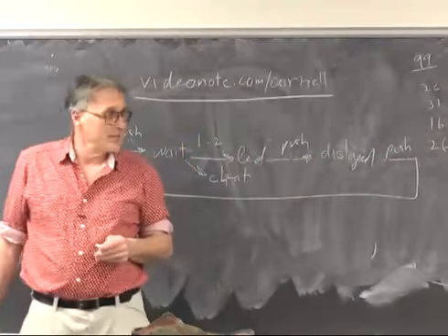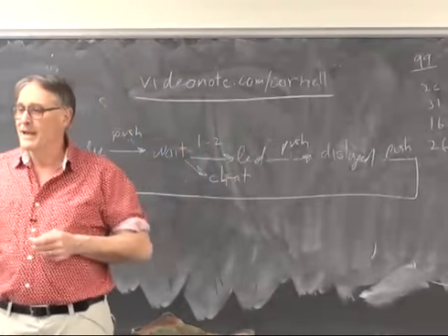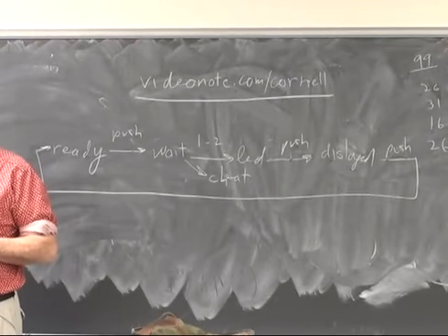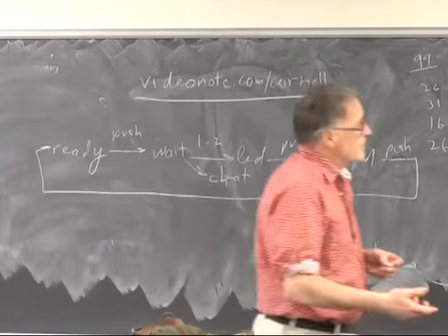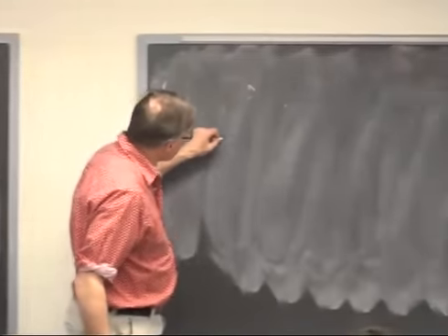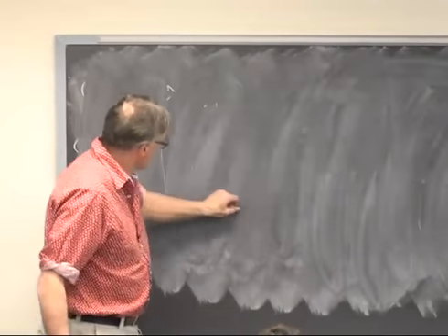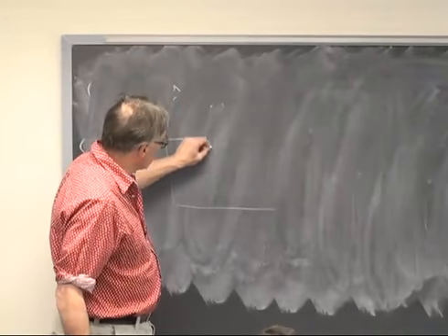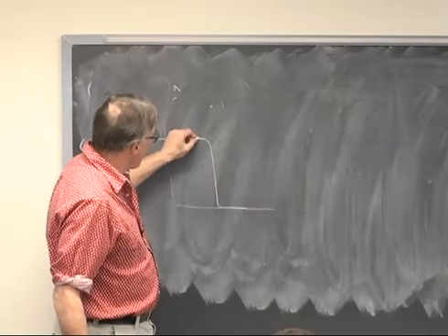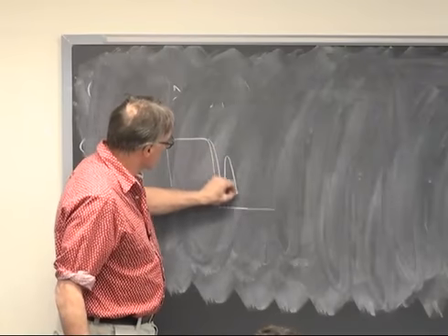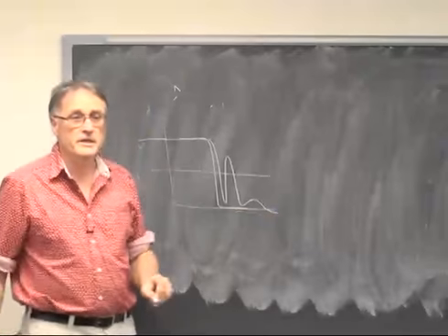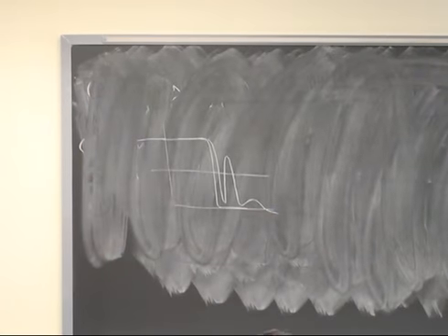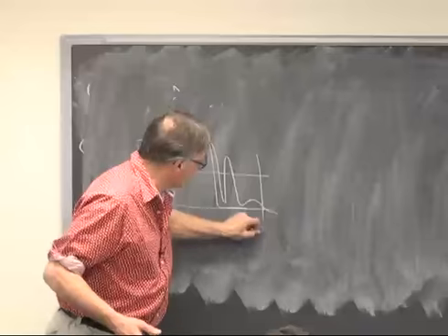Now, the thing which makes this interesting is that mechanical buttons all bounce. They're spring mass systems. They oscillate. So when you push a button, you think the voltage should do this, but in fact, it does this. And it can pass the CMOS transition voltage n times in about 15 to 30 milliseconds or so.